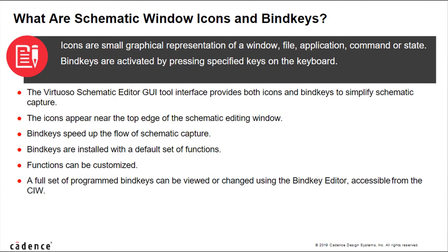You can click on different buttons in the Schematic Editor toolbar, use menu items or even keyboard shortcut bind keys to simplify your schematic capture. The icons appear near the top edge of the schematic editing window. Bind keys are activated by pressing specified keys on the keyboard, which speed up the flow of schematic capture. They can be installed with the default set of functions, and these functions can be customized.